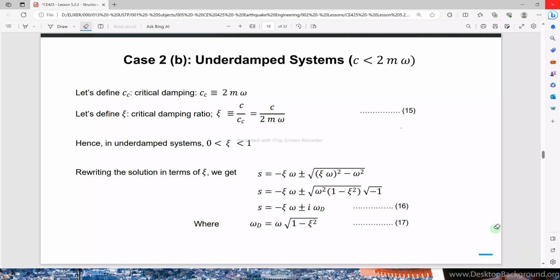Okay, so because of the discussion, we have added some limitations here. So we have here the critical damping ratio and then the critical damping Cc. Here, the critical damping ratio is actually our decay function. It will show us how fast a structure dampens.